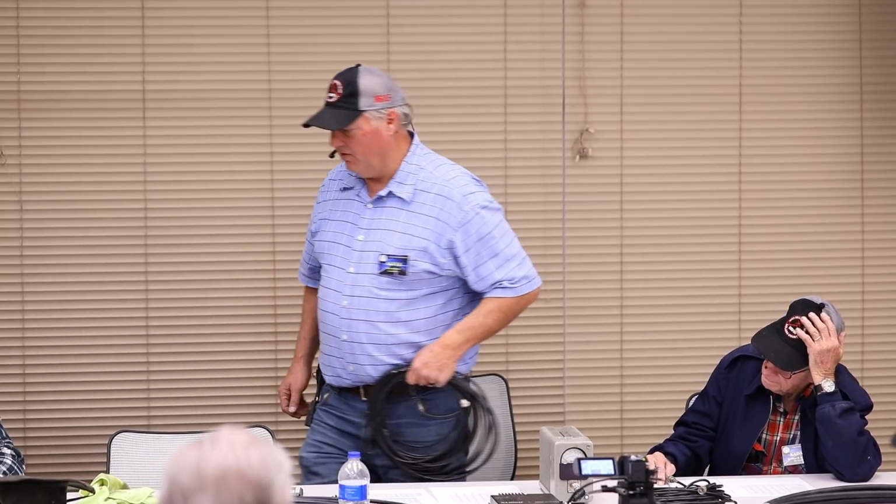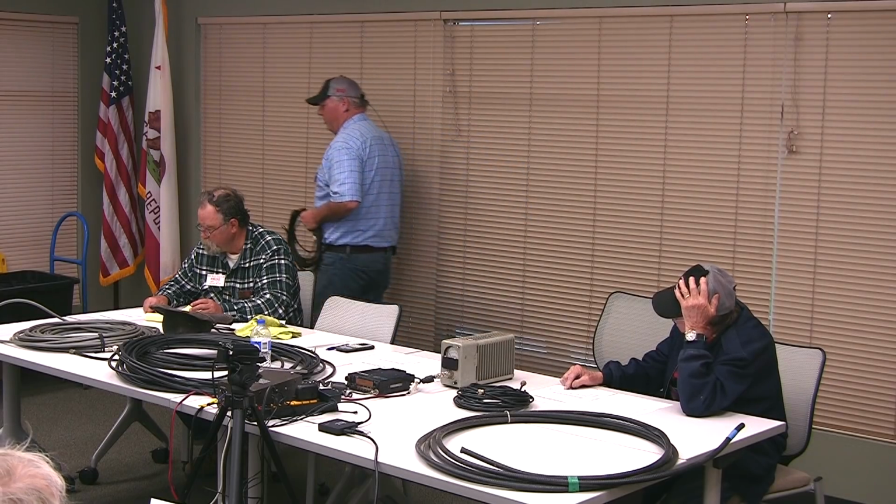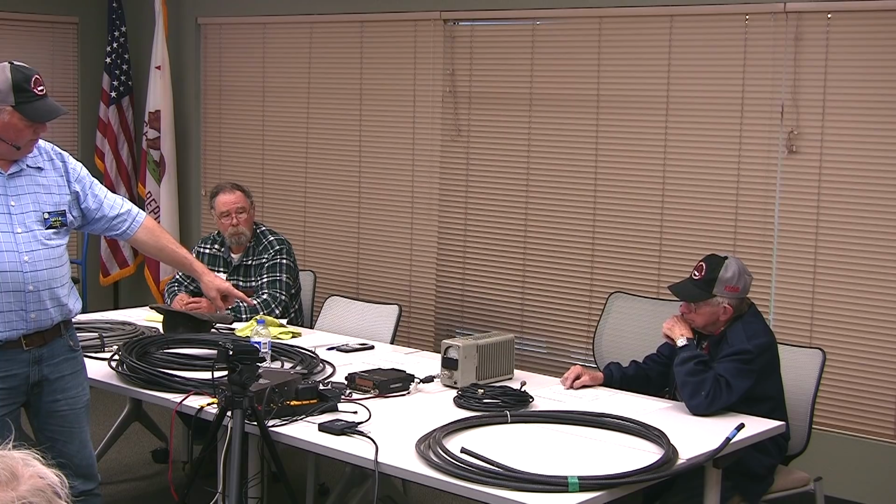So I often get asked, well, what does that really mean to me? Well, we're going to do that right now, and we're going to do some cables. I'll tell you what cable we're doing and how long it is. You could look at your chart, and you can pretty quickly estimate what the loss is going to be. And we're going to do it looking at that Wattmeter, and we're going to do it with a dumb old 30-year-old Alinco radio.